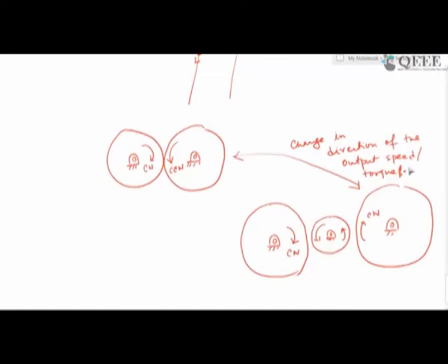But that is not possible for a four-wheeler because it's too heavy for us to do that. So you need an arrangement which will provide the mechanism by which the output can be reversed. And that arrangement is pretty easy to attain. You just have to put an idler gear in between the input and output. And that is exactly what is shown.